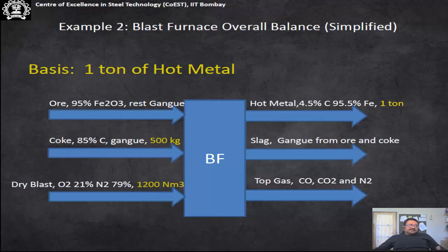Using the ideal gas law, it again becomes the mole percent. As far as the gas amounts are concerned, they are expressed in normal meter cube, that is, at 273 Kelvin and atmospheric pressure, what will be the volume?